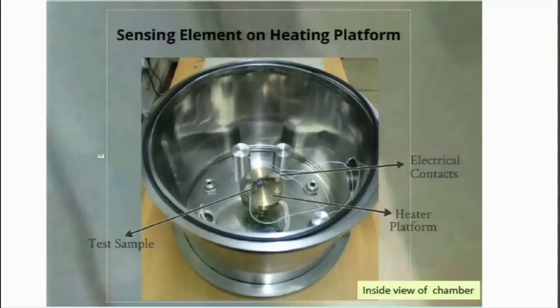platform here which does gas sensing inside a vacuum chamber, which has a heating stage. Remember, all these elements are highly sensitive at a higher temperature. That is the biggest problem with gas sensing: semiconductor metal oxides or even metals cannot sense as well at room temperature as they can at slightly elevated temperatures, 190 degrees or 180 degrees, for example. In the present case, it will be about 180-85 degrees, at which sensitivity will be the highest in this particular case.